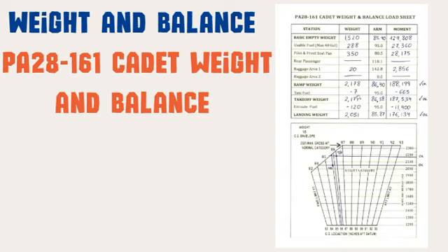This is the aircraft weight without any passengers, baggage, or usable fuel, but including hydraulic fluids and unusable fuel. Usable fuel. This is fuel that can be used, with a maximum of 48 gallons. Pilot and front seat passenger. The combined weight of the pilot and the passenger in the front seat. Rear passenger. The weight of the passenger in the rear seat. Baggage area 1. This aircraft only has one baggage compartment, which is accounted for in baggage 1.